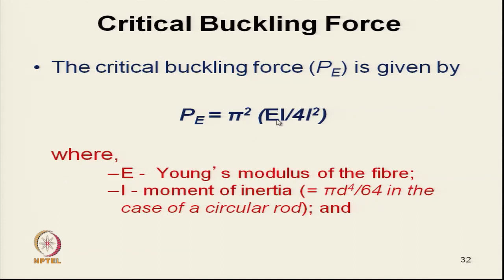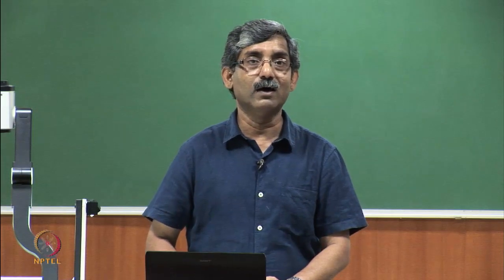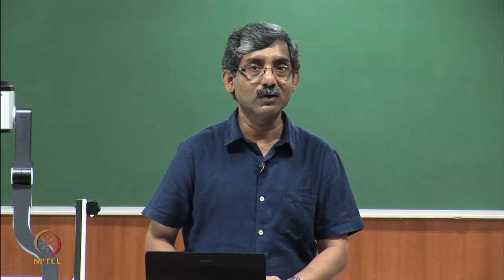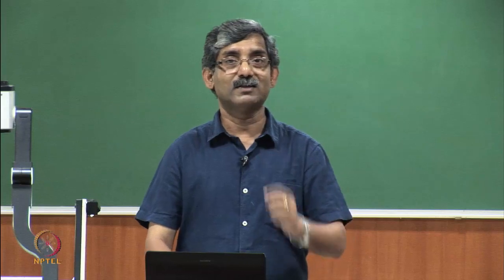So, if the fiber diameter is more, as we have discussed earlier also, it will create hairs, and if the hair is created with a higher diameter, it will give a higher moment of inertia, and the buckling force will be more, which means it will create the prickle sensation.